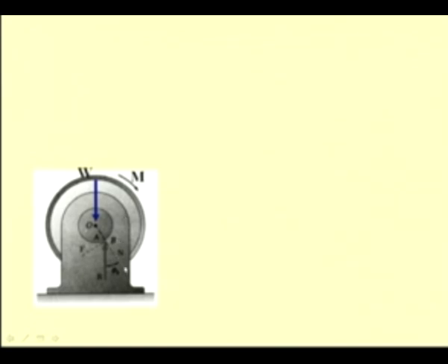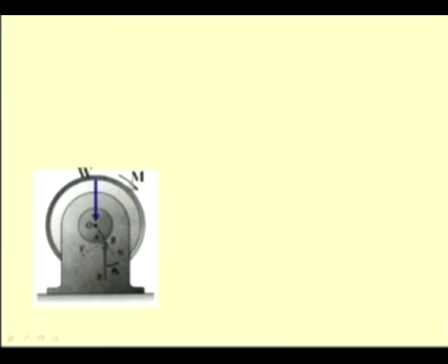That means the wheel, which is revolving or rotating, will come to a stop if this M is not applied. So, to keep this wheel in constant motion, the clockwise moment M has to be applied. We call this the frictional moment that has to be overcome in the journal bearings.